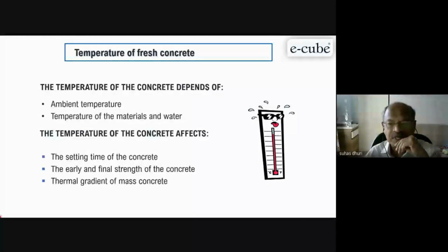But we have to remember temperature of concrete is also important. And whenever you are maintaining the temperature of concrete using chilled water, or sometimes you use ice flakes also, it is very easy to pump. It requires a very low admixture dose because loss of workability is low. So we can save on your admixture consumption. So that is also possible.